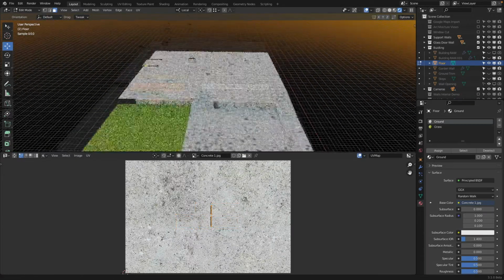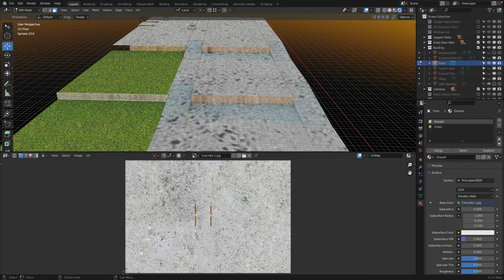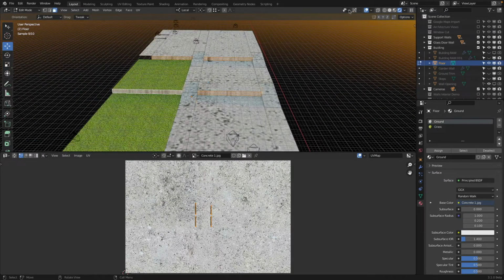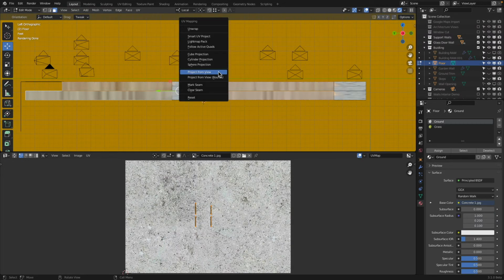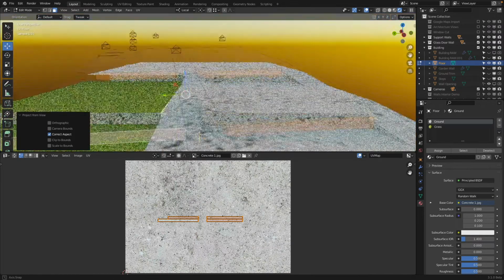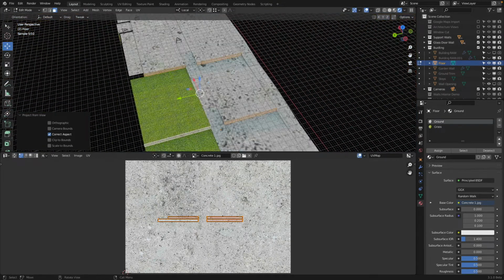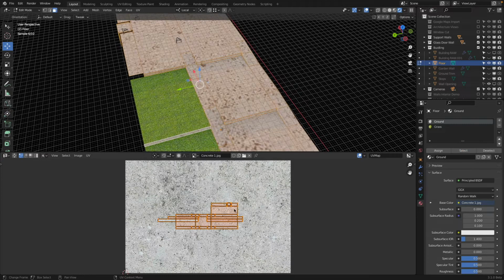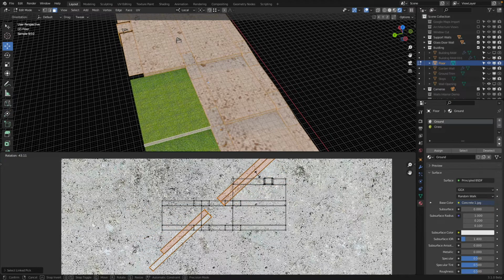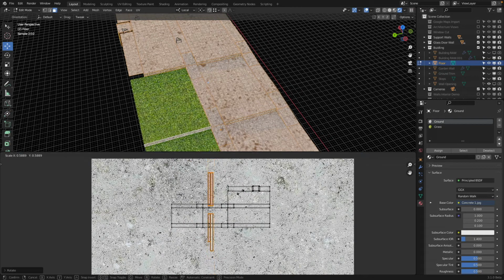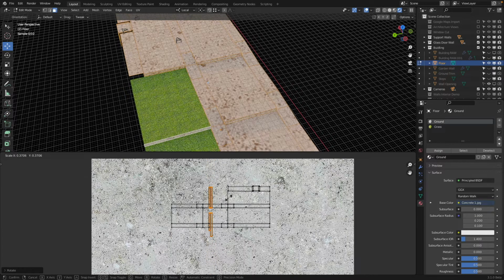These views then are actually broken, but what I can do is I go from this view and say unwrap from view. Now you see they're rectangular again. Okay, and then if I select all, what I would need to do is L and L and L and L. You see how I shift selected them? I can press R and this is probably minus 90. Okay, and then S and I scale this one down.